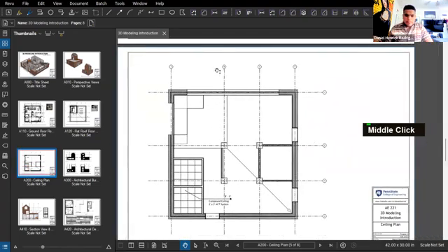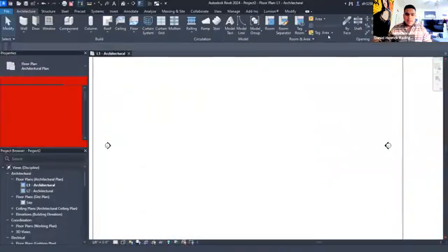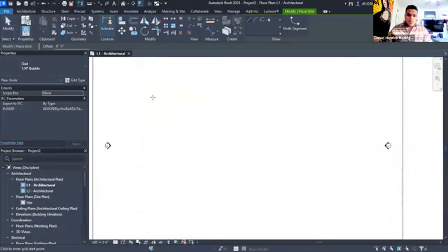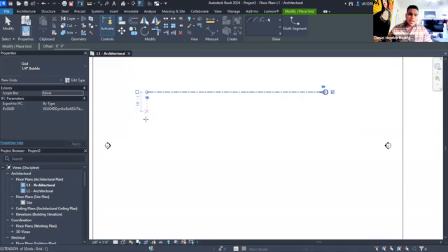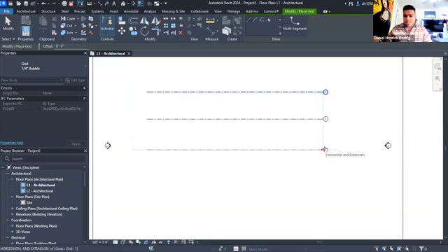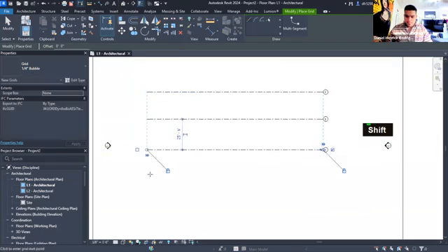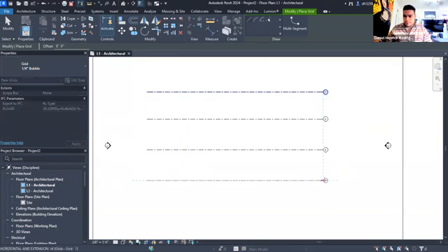Okay. Let's go back to our Revit. Click on the grid tool. We're just going to go from left to right. Right to left also works. Either way, we're going to put down 1, and then you're going to come down below the first point that you put down, 2, 3, and then you're also placing exactly where you left off. If you're having trouble making it straight, holding Shift makes it so that it's straight no matter what. Okay. So we got 3, 4.